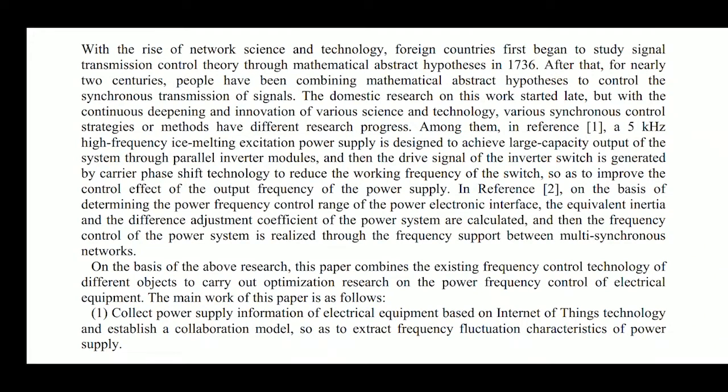In reference 2, on the basis of determining the power frequency control range of the power electronic interface, the equivalent integral and the different adjustment coefficients of the power system are calculated, and then the frequency control of the power system is realized through the frequency support between multi-synchronous networks.